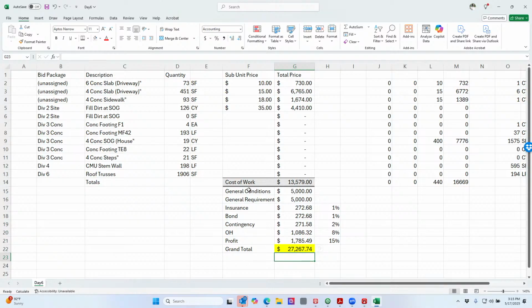You also have my estimate template. Okay? So you can do that. So if you're trying to do something hot and quick, use my estimate template where you can say yes and no if the scope is covered by a sub or not. So you would use something like this for like a phase 2 estimate where you're just trying to put together a rough cost. When you're hard bidding, you probably want to use the detailed estimate template I provided for you so you can actually say, hey, yes, we received a bid. I don't need to carry my number. I'm going to carry the sub's number.